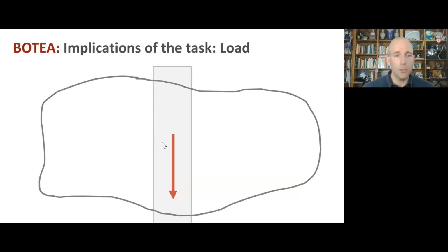So here's the edge of the door. Here we're looking at the door edgewise. And this is sort of an imaginary robot with no features. And I know that I want this downwards force from the payload, that I want that to be big. Well, the rules are that we can't touch any surfaces that aren't vertical. So that means we're going to need some kind of friction force on those vertical surfaces on the edges of the door to counteract this downwards force from the payload.